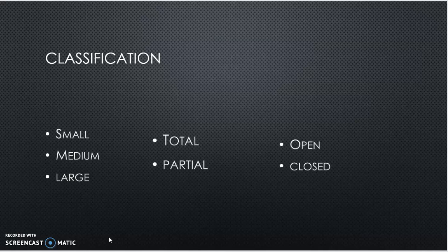Meaning you are constructing a lot of health centers, a lot of schools or anything typical. And the architecture is having a repetition, or maybe it's a symmetric plan, or a plan which is going to be adopted everywhere. And there has to be sufficient demand. Although all the schools can have the same plan, there have to be many schools first and foremost. If you're going to have the project only in one place, just because the plan is repetitive or the size of the project is very large, but it's just a single project, you cannot go for closed prefabrication.